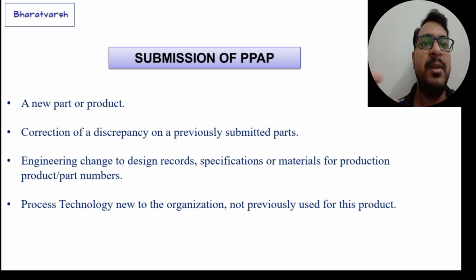When do we have to submit the PPAP? If there is a new part or product, then we have to submit the PPAP. A new part, like an initial part at the time of development, or maybe an old part but with a new part number. Second is when there is a correction of discrepancy in parts which were supplied previously,